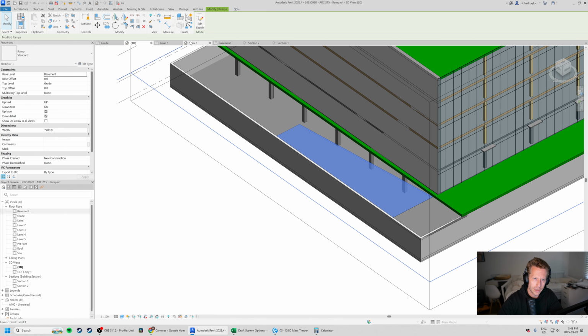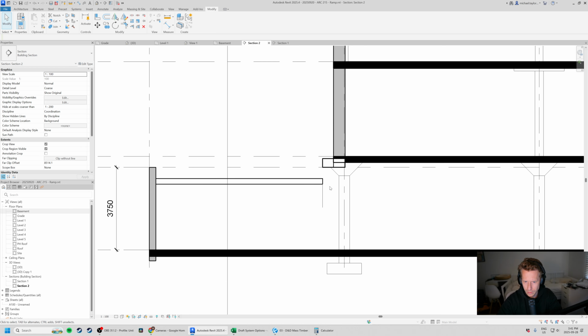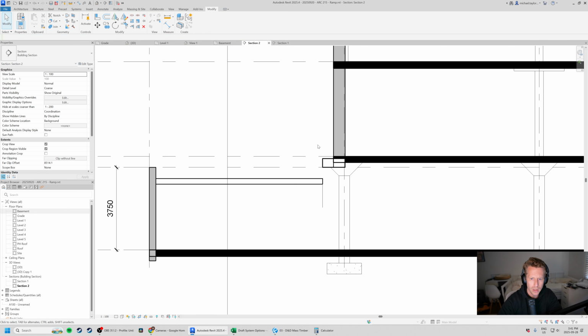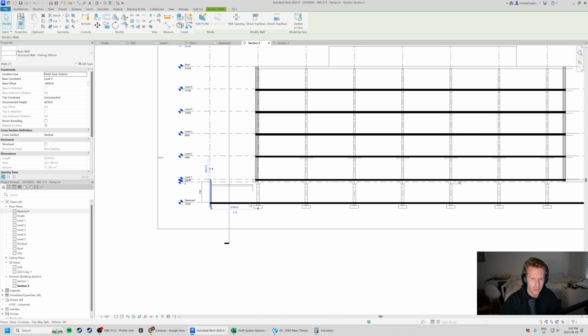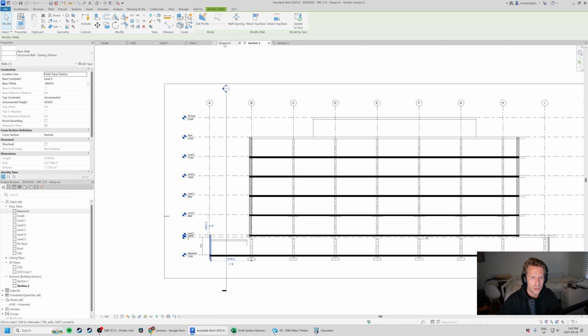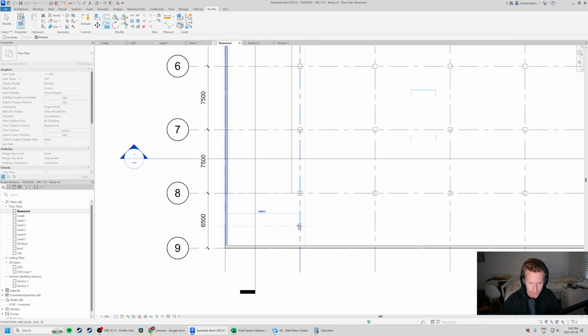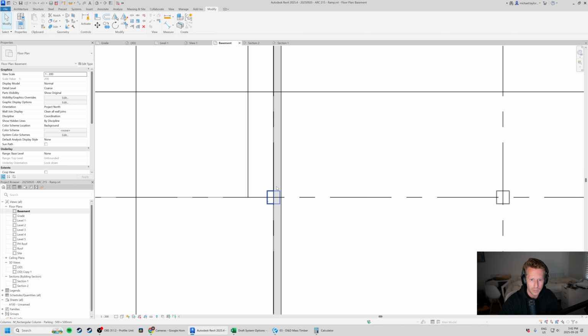Looks pretty good. If I jump back to that section, we should see it's looking all right. We would normally probably push it all the way to some sort of structural wall in here. So we should probably also have a structural wall along, what's this, grid line B. So why don't we jump to the basement here and make a structural wall along grid line B. You can copy it. And I probably want to align one of these faces. So align is AL, remember, for align. And I will try, why is it not letting me do that?